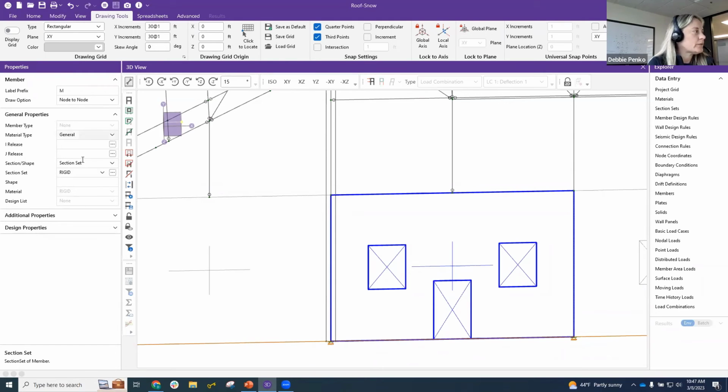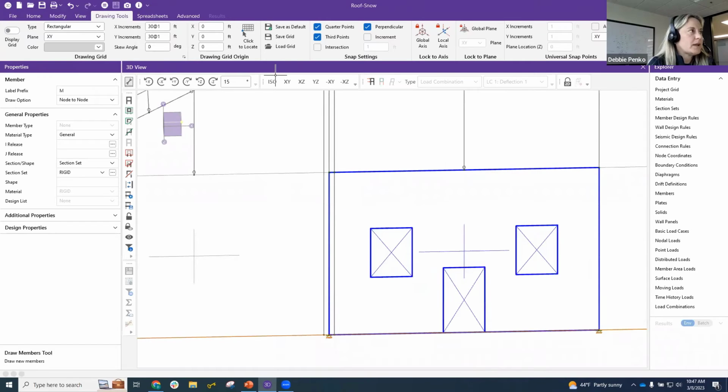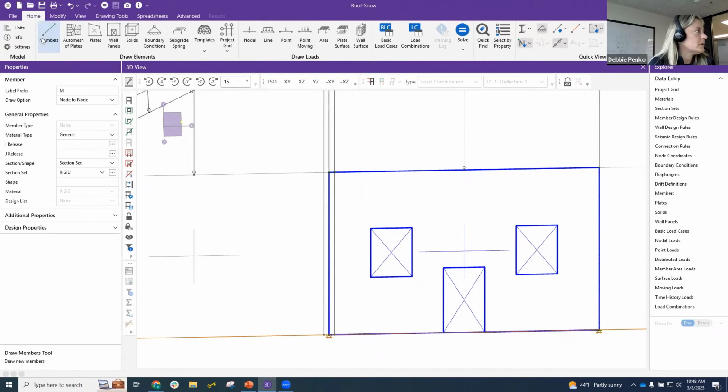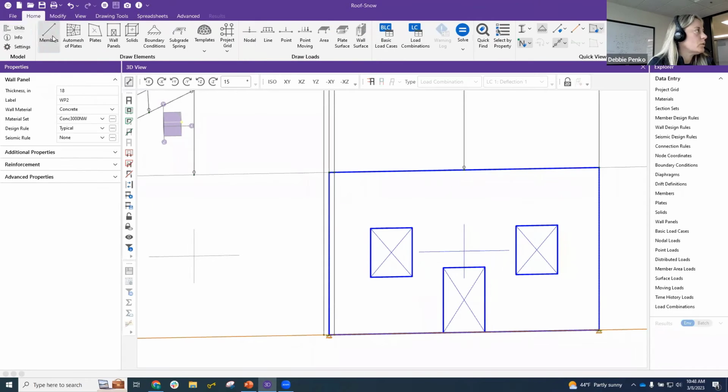So it's this little general rigid link. And I just start drawing it from the original column location to this new corner point. I do need it to be perpendicular, so I use that little perpendicular tab button there, and I click on that and connect it. I can do it on both sides, so it's the same repeat right there. So I'll click on draw.